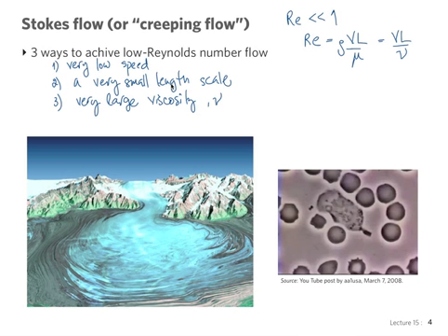This second order term, if you will, if the velocity is tiny, smaller than 1, you can neglect it. And so you get a simplified form of the equation, which is called the Stokes equation, which is linear. And in the absence of nonlinearity, you can get exact analytical solutions in many cases. In most cases you can. So it's always going to be laminar.